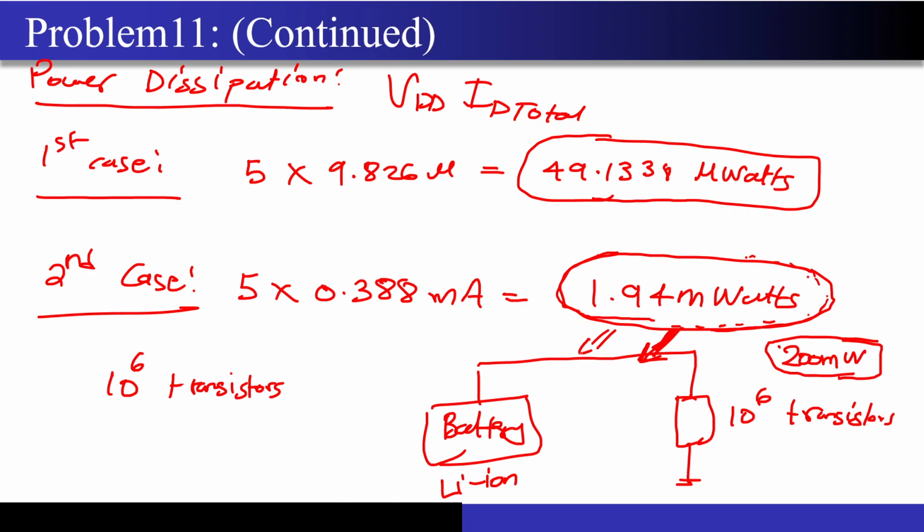But you can clearly see that they are still consuming around 0.388 milliamperes of current. So even if your processor sits idle, this much current will be consumed and your battery will drain out, because the processor constantly consumes this much current, and you will start thinking why your battery is draining so quickly.